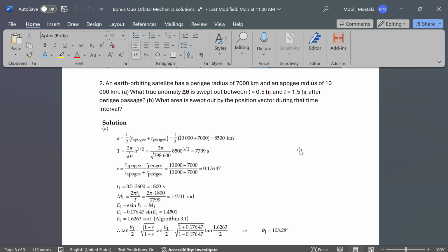Sure. In general, whenever you're given a theta and you're asked to find a time, or vice versa, which is the vice versa part here, right? This is an elliptical orbit. We have RP and RA, you don't even need to calculate E, we already know this is an elliptical orbit. In general, let's say you're given a time, you have to calculate the mean anomaly of the elliptical orbit, and using this you have to calculate the eccentric anomaly, and then you calculate theta. Right? This is how it's going to go.